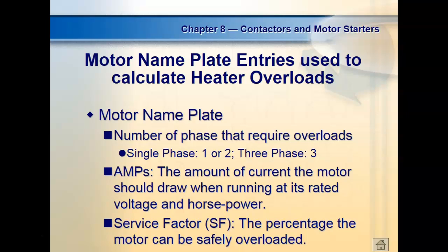So probably y'all plug your ceiling fans all the time, right? Anybody got a ceiling fan? Anybody reverse it? What does it do when you reverse it? You flip that little switch and it's pulling quite a bit of current, right? Because it's pulling starting current basically, or a little more. So that's called plugging. Some motors are designed to be plugged. These are the motors that are going to have a real high service factor, like 1.5 or something like that. A motor that's got a service factor of 1, you need to let it stop, especially if it's under load.